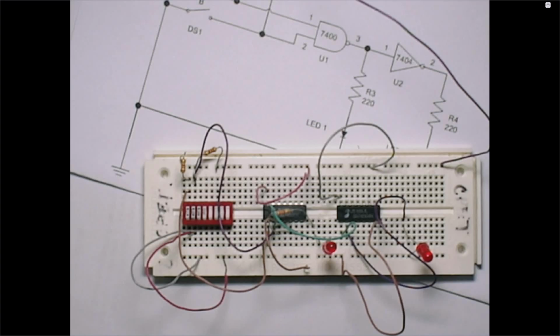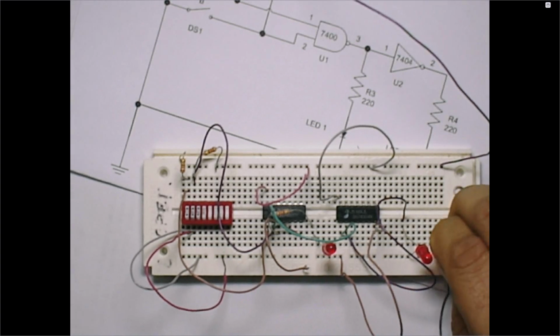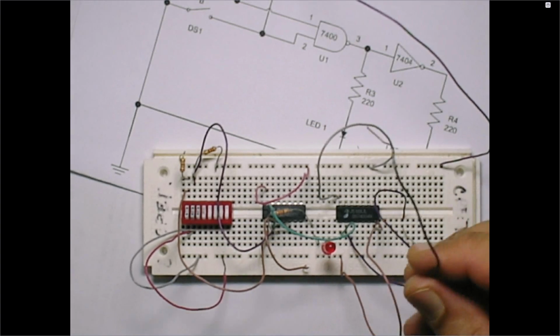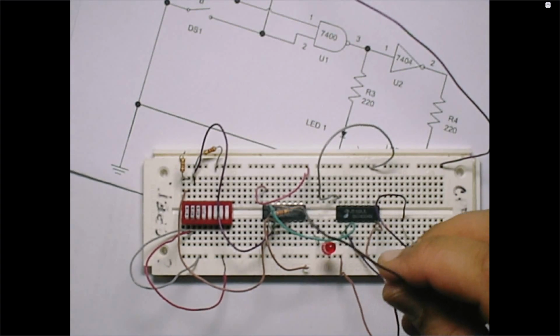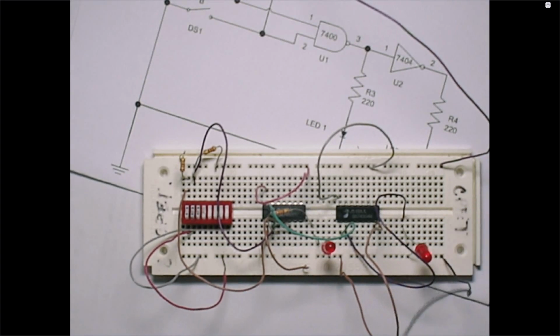And for the ground row, you need the ground, connected to the voltage 0, right? So let's do that. You can choose any point from the ground row. Let me choose this last point here. You can choose any point, okay? And then connect this open wire through the alligator clip with the voltage 0. Now once you do that, your circuit should start working.